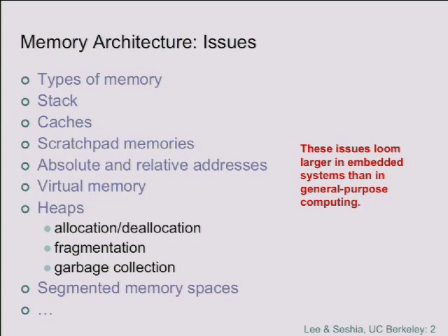By the way, Boeing had to make sure that the microprocessors were made on the same production line. It was not okay to have one subset made in Palo Alto, the other subset made in Taiwan, even if they're the same brand of microprocessor, okay? They also had to make sure they were made from the same mask set, so no bug fixes in the mask, please, okay? And they tried to buy them all in 1 week so that they were made with the same chemical processes in the plant and so on, okay?